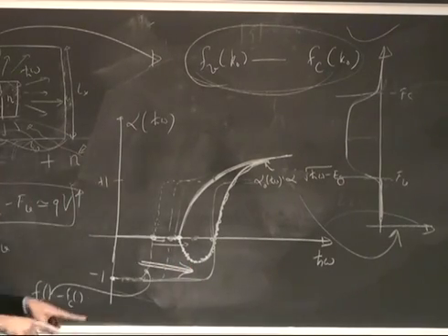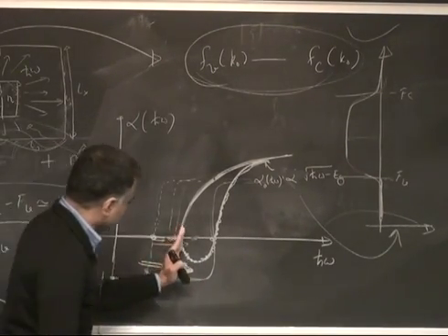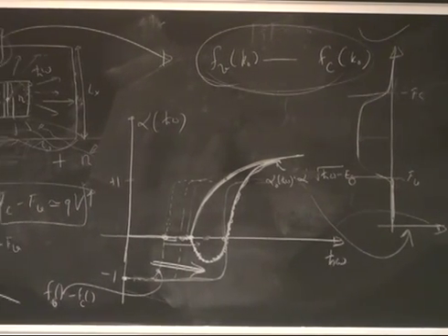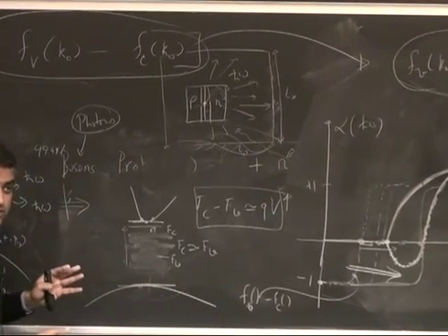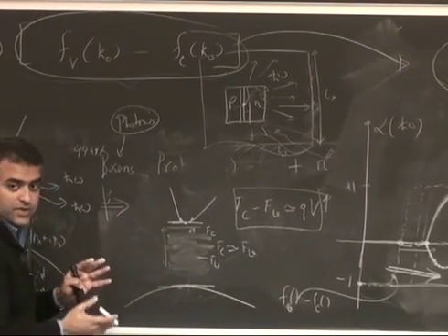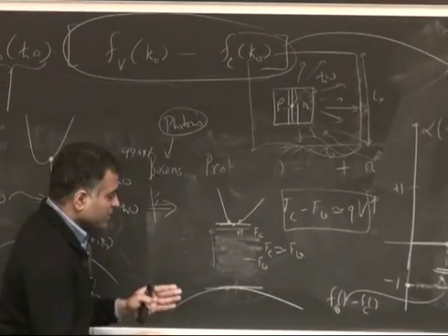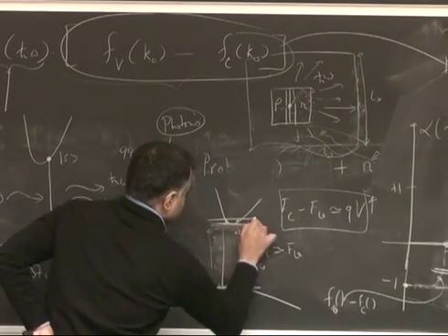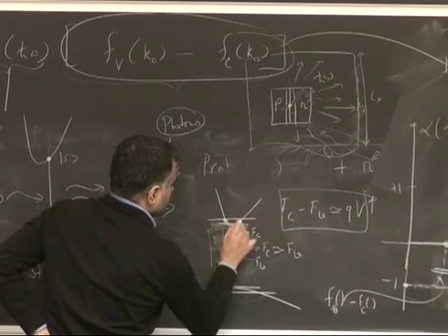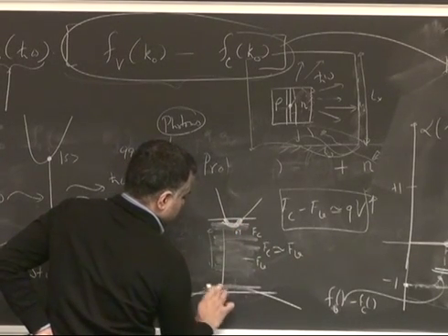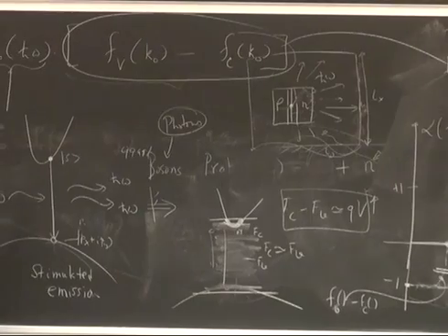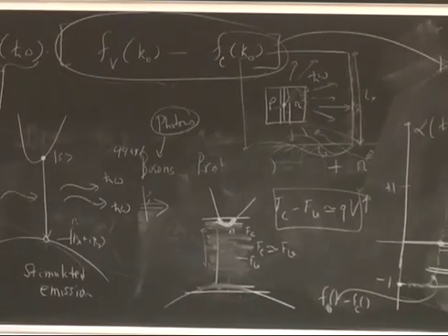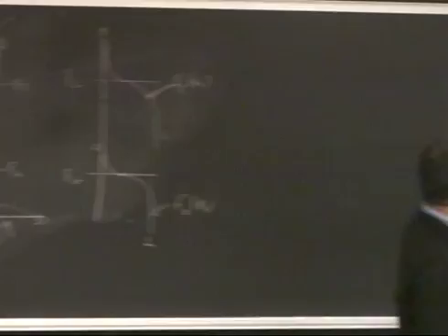Essentially, by injecting more and more carriers, I reach a certain threshold of carrier density. And when does that threshold happen? That's when the Fc gets into the conduction band and the Fv gets into the valence band. So what you have done really is made the semiconductor degenerate, and just to make it a little more clear, you have occupied all these states and you have unoccupied all these states. So this is the population inversion. Inverted the population, and that's what's shown here. Fill these conduction states with electrons and emptied out the valence band states, and that happens.